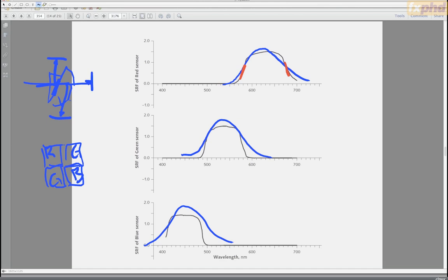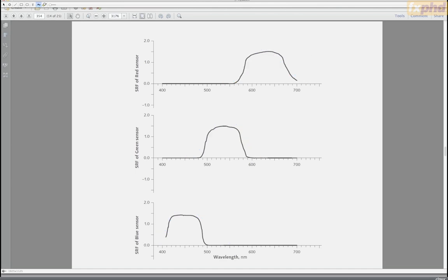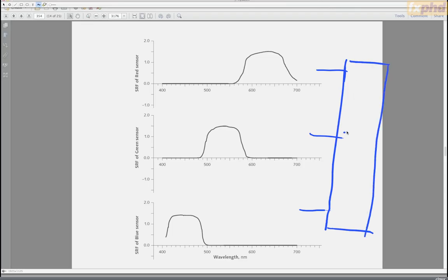But nonetheless, in a camera, even an old one, and certainly a new one, we start with curves like this. And we take those curves and we basically add and subtract each channel from the other judiciously, a little bit like I showed you a moment ago, to produce the signals that we call R, G and B.